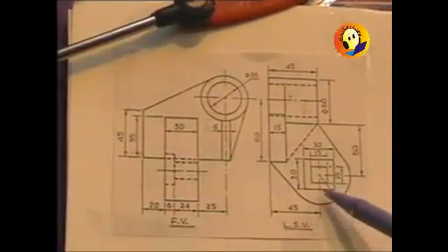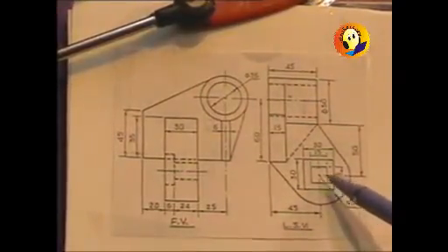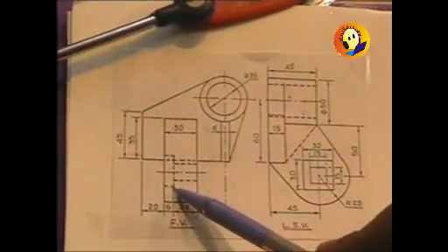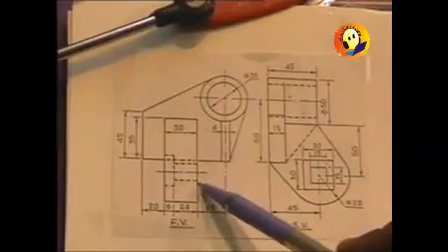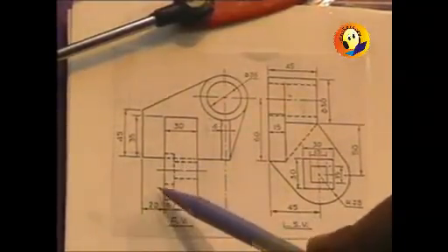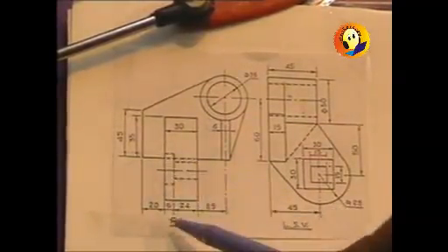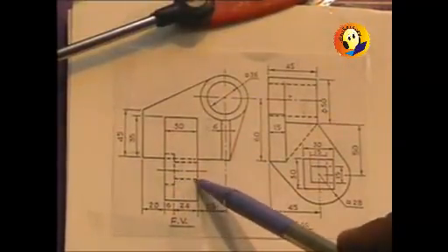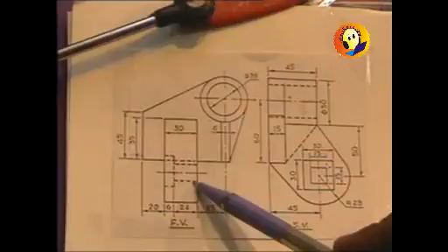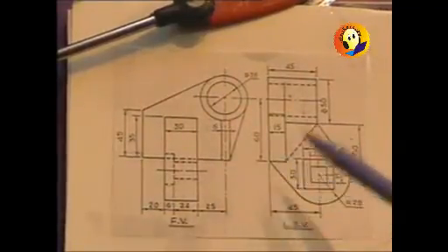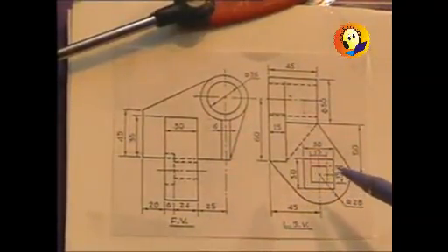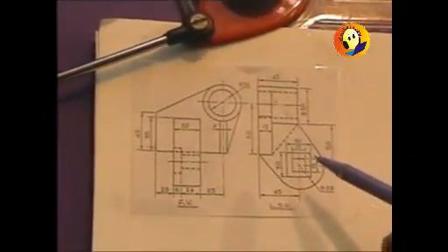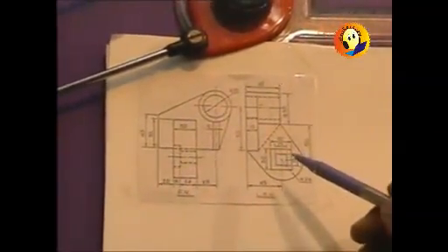There are two squares which are shown, and corresponding to them you find that there is a dotted line over here corresponding to the bigger square, and a dotted line over here. That means both of them are actually square holes. One is of depth 6, whereas the smaller square is of full depth, 24. Once this interpretation is through, then we can go for the rough sketch of this particular object, which is going to be a very small sketch.